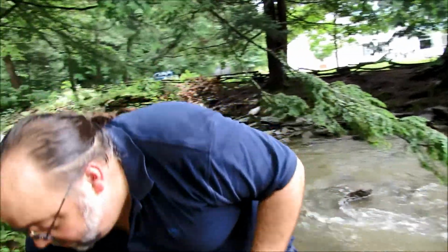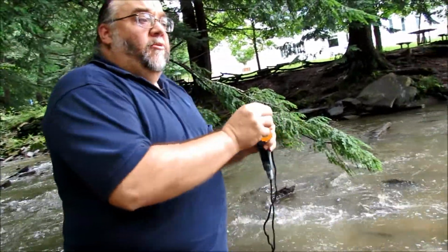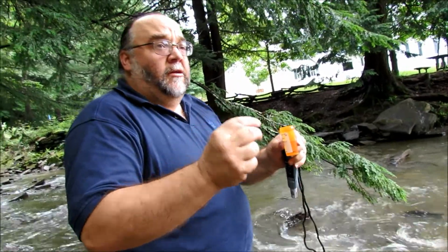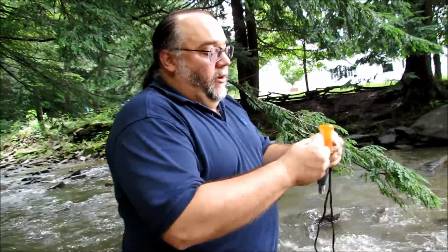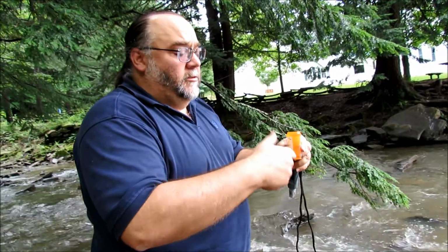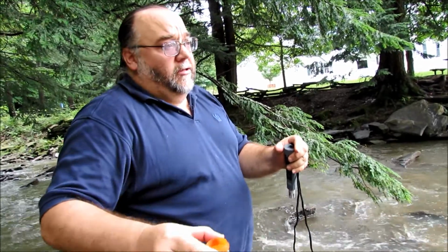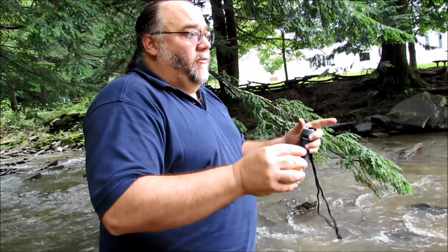If you're going to reuse this for your sampling cup, you'd want to dump it and then rinse it 3 times with the water that you're sampling. When you rinse it 3 times, it's better to rinse a cup like this by filling it up halfway, mixing it, dumping it out. Let's say we wanted to rinse this.